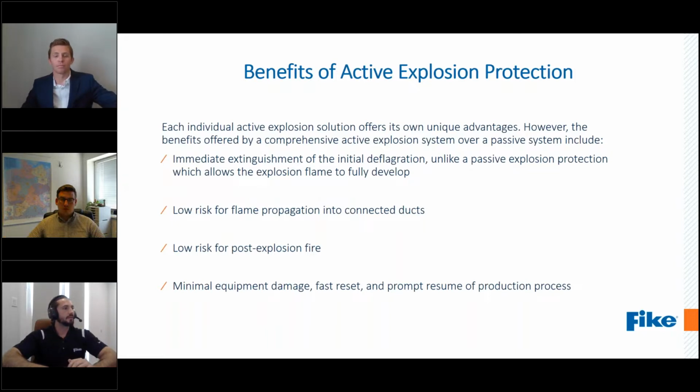And finally, a few additional benefits relative to passive. We do have to keep in mind that active systems usually allow for the immediate extinguishment of an initial deflagration. It stops that deflagration from developing any further momentum, whereas a passive system allows it to run its course. So a little bit different strategy there.